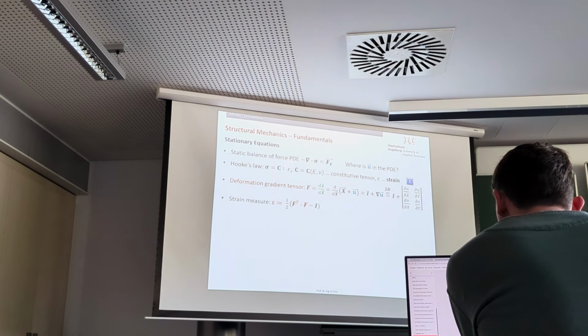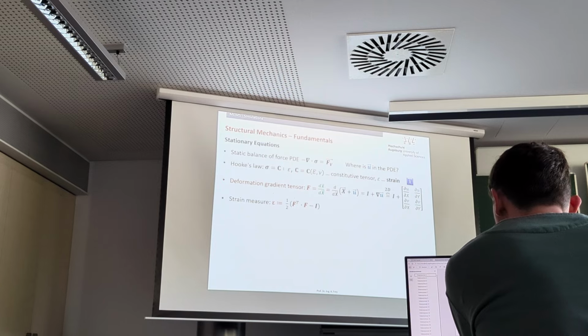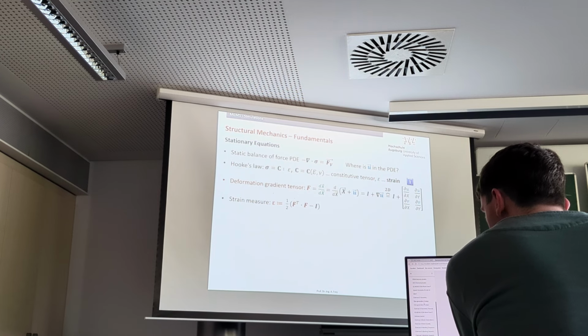It means nothing more than having the stretching transposed, which technically is a matrix in which the off-diagonal elements are just flipped, then the rotation transposed, then we have F, which is just U times R. And now you can rewrite this, just changing the order, which is something you can do with matrices, and then we have this times this. This is interesting, and I'm not sure if one of you is familiar enough with this to interpret what is going on here.